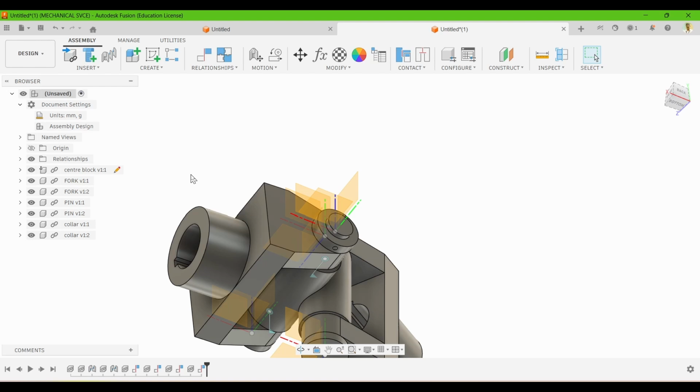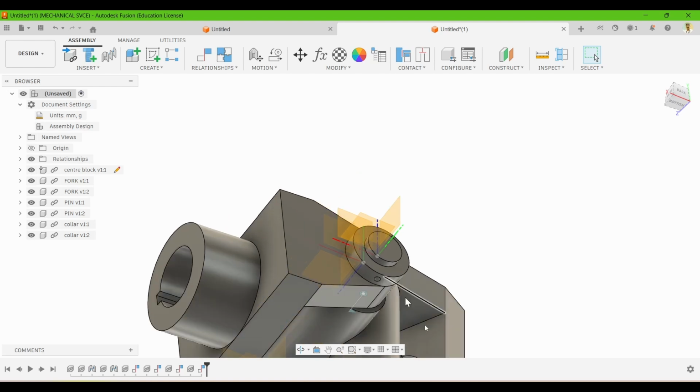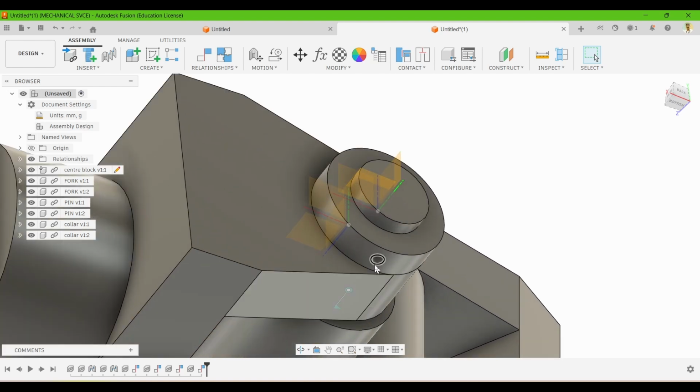That's it. Okay, if we refer the figure, real figure, the diameter of the hole will be 5 mm, but the taper pin will be 6 mm. Okay, so it is like interference fit. It is not regular clearance fit. It is an interference fit.